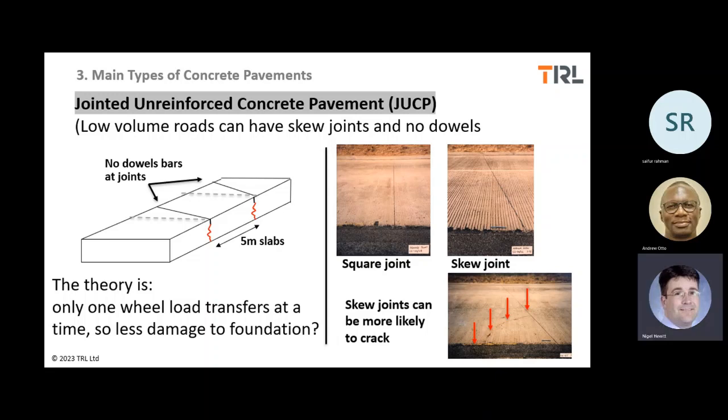This is a variation on that. For very low volume roads, some people have used no dowel bars, so there's no load transfer. But this is only for, I would say, rural roads with no heavy goods vehicles.